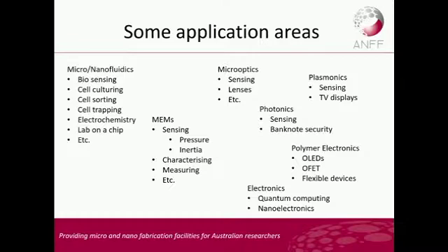And when I'm talking about design today, I'm talking about planar technologies, where we use a clean room, where we use photolithography, etching, deposition, and we do cycles of these different processes in order to build up a device. I mean, we do have other capabilities. We've got 3D capabilities as well. We've got two-photon lithography. We've got other 3D printers that we can use to make 3D structures. And we might touch on some of that today, but mainly this is about planar type technologies.